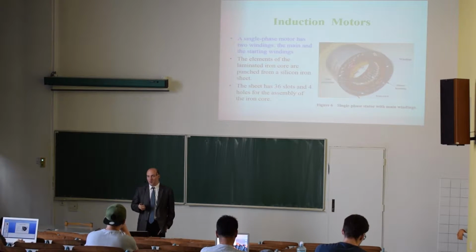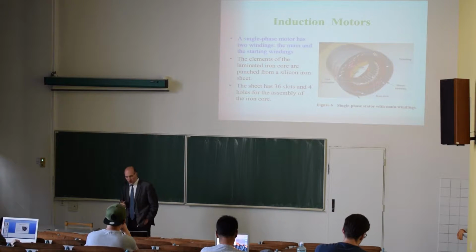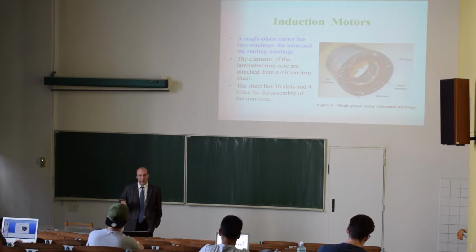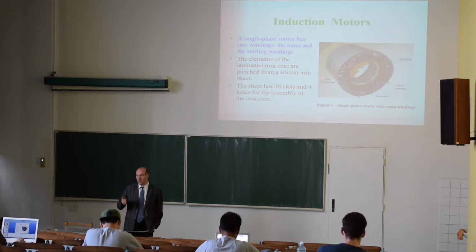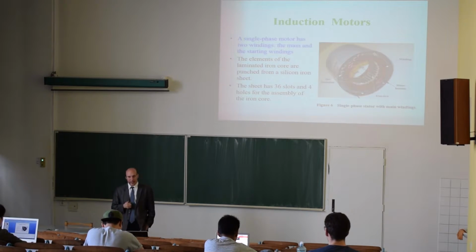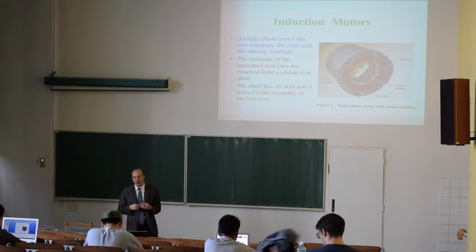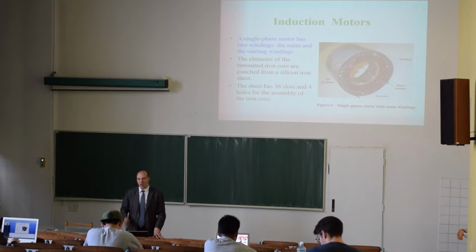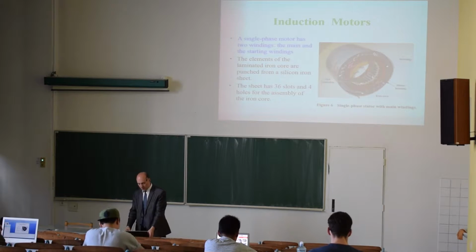That's the main parameter. So when we want to control the speed of the motor, we will have a stepwise control if we change frequency or if we change construction. If we will be able to use electronic circuits to create some variable frequency, we will be able to have a variable speed drive.